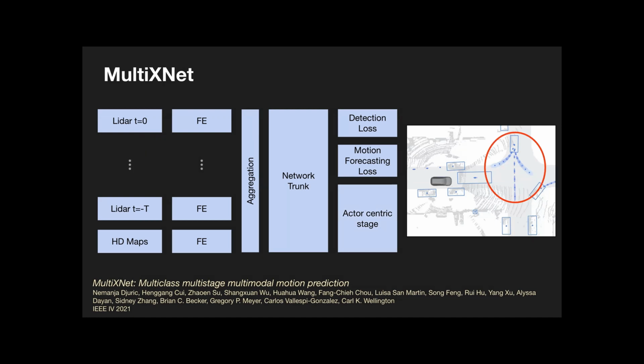This can be seen in the right picture as blue shaded ellipsoids, as well as the addition of multimodality for motion forecasting. You can see in this example that we want to capture all likely paths the car could follow when crossing the intersection. In this case, it could be straight, left or right. Multimodality and uncertainty estimation are very important for self-driving applications in order to get a better coverage of the future motion states. The planner needs to reason about the different possibilities the actors could do, as well as the confidence on these estimations.